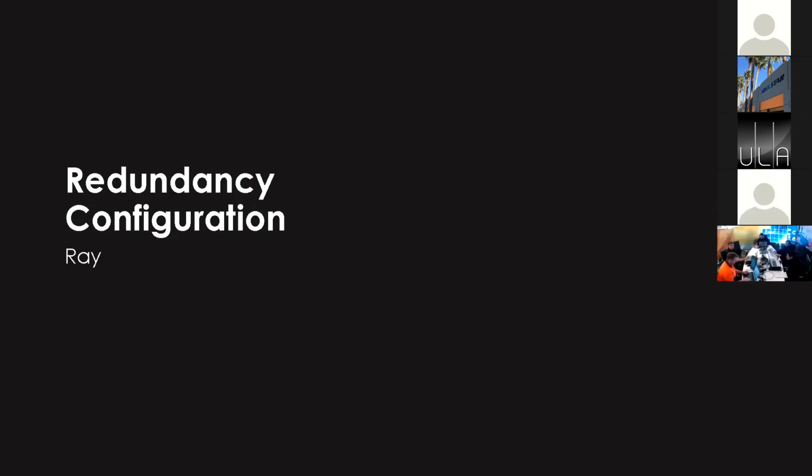I just wanted to have a bit of a chat before we kicked off officially. I know there were some questions yesterday around RCFG files and high refresh rates and different configurations and things like that. Basically, to make your own config, yeah, it's possible, but you really need to know the layout and the ins and outs of the particular module to build them. 99% of the time, you just want to do a readback from when you first get the cabinet file from your vendor and save that file. Normally, they'll ship those files with the panels as well.